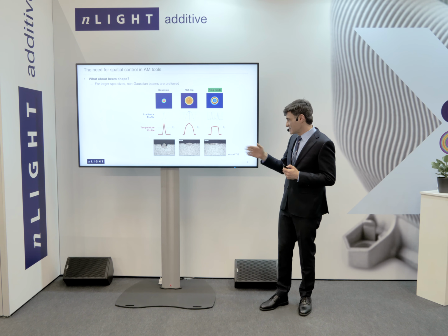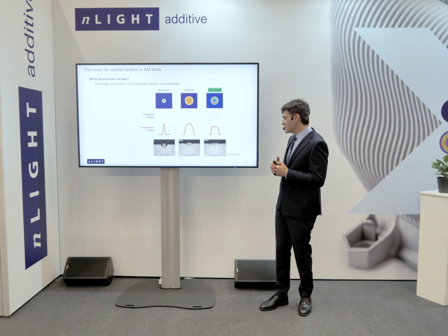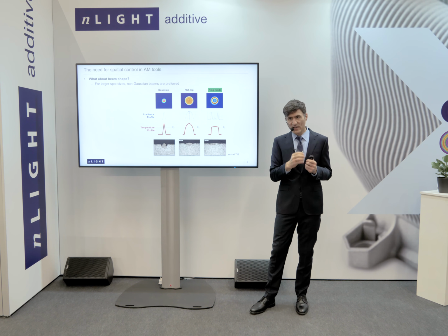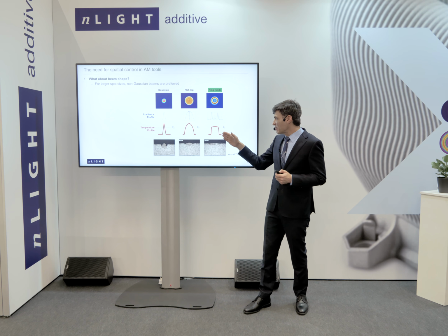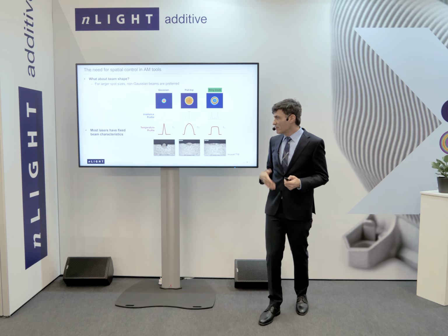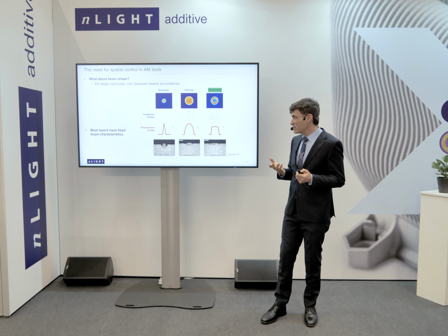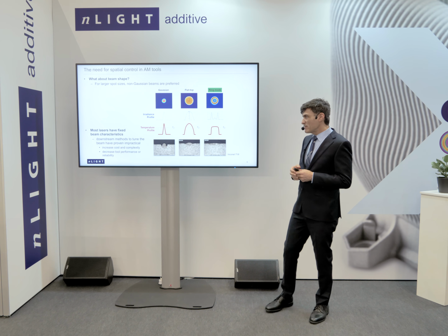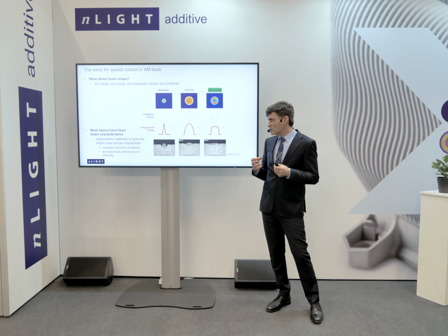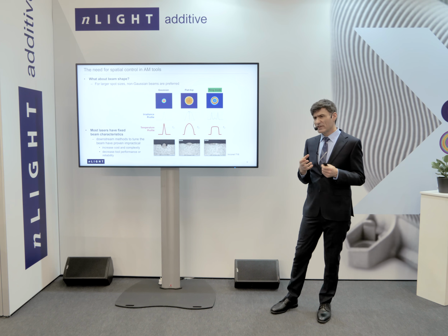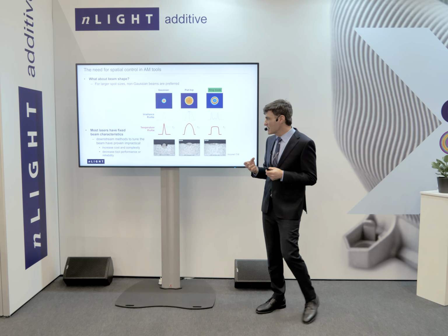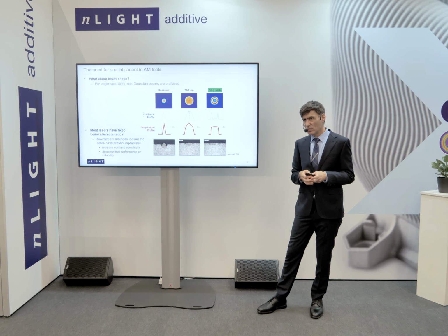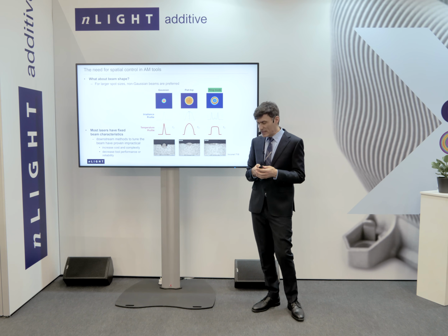Maybe getting ahead of ourselves, this effect is actually shown here in laser powder bed fusion of an Inconel 718 part, where you see the peaky temperature profile gives a balling of the material, and you can eliminate that by going to the more ring-shaped profile. Unfortunately, most lasers until now have had fixed beam characteristics, and so you couldn't take advantage of this effect. Various downstream methods have been introduced to tune the beam profile, but they've largely proven impractical. They often involve free space optics, and they increase the cost and complexity and or decrease the performance and reliability of the tool. So although these methods exist, they haven't really been widely adopted.